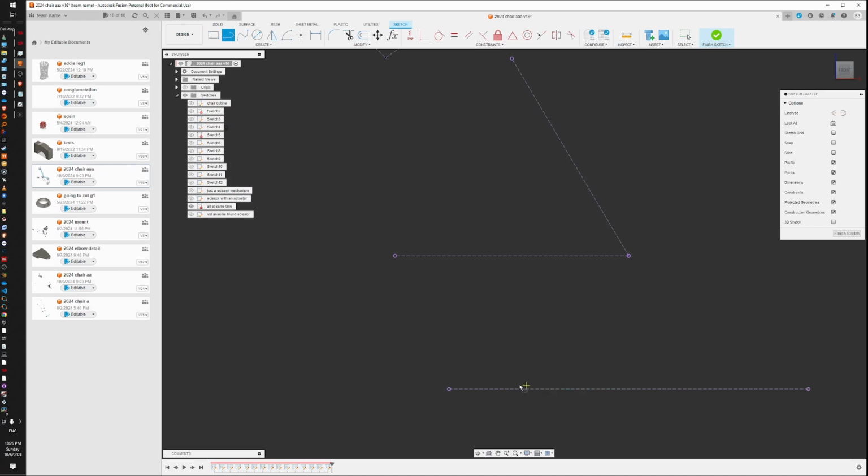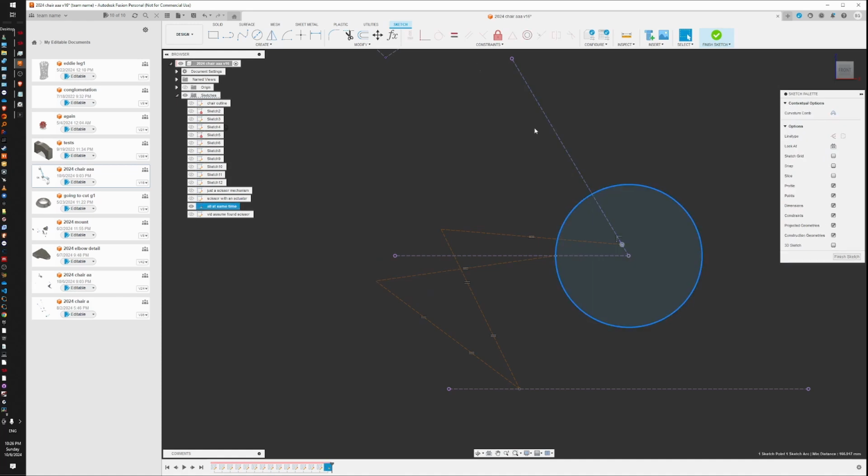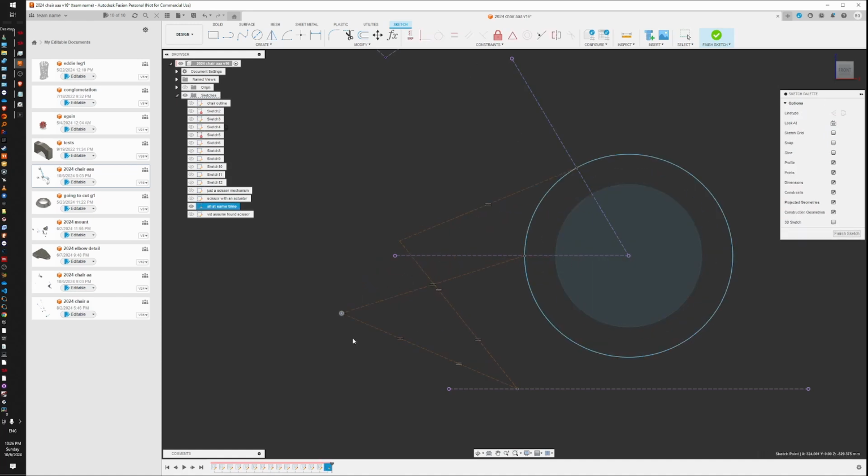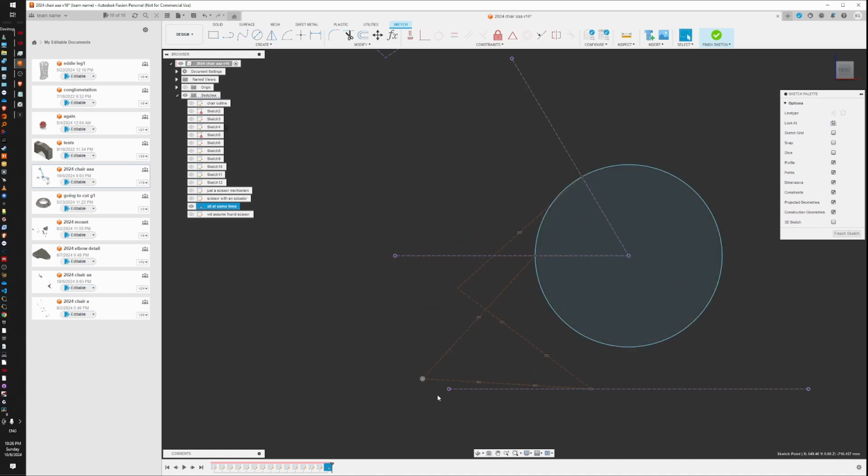It's a little bit involved, but I want my scissor mechanism. So that's the contracted, that's the extended, and let's just make it easier to see. All of these need to be the same length, so I will just do that. There we go. Now they're all the same length. A little bit wacky. I want the distance from this point to this joint and this joint to be the same. So I'm going to use a circle. That's a little bit hard to see. All right. So yep, now they're all on that.